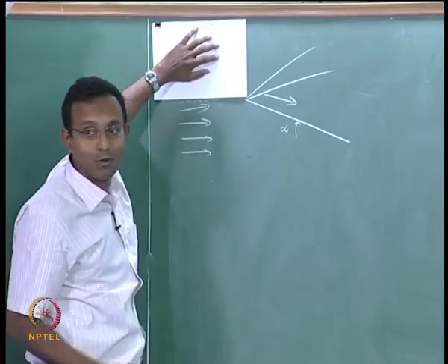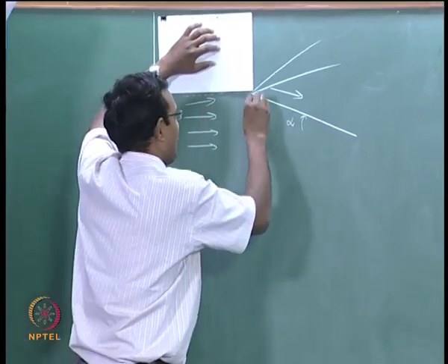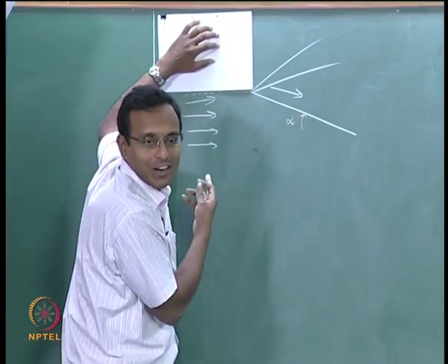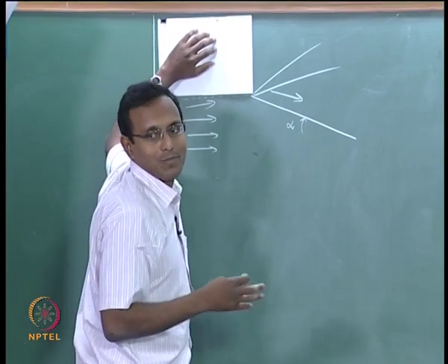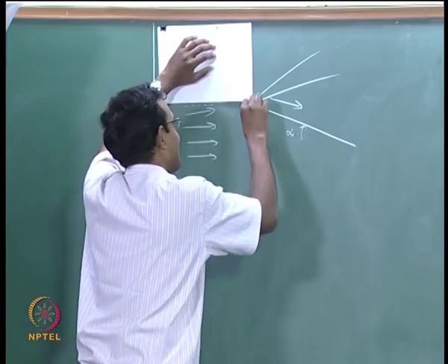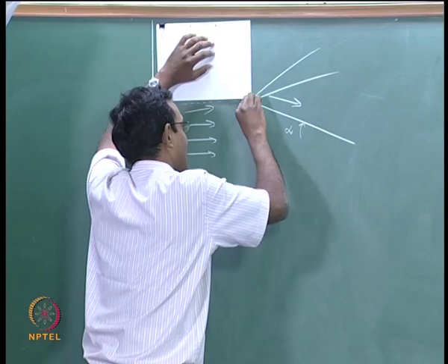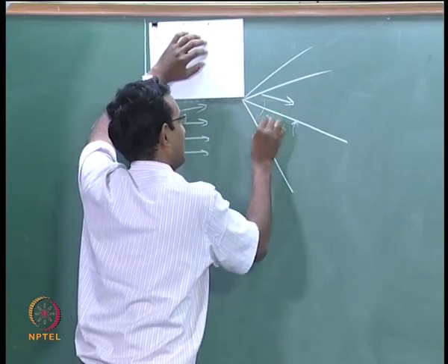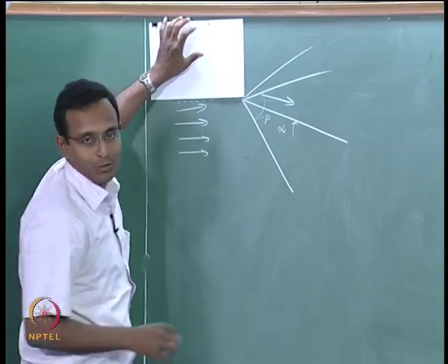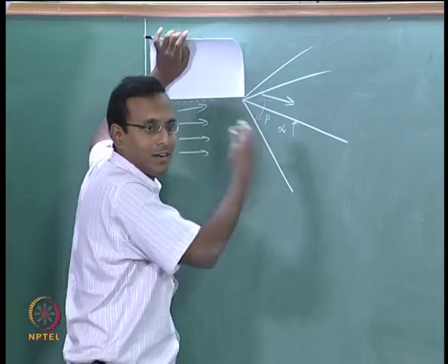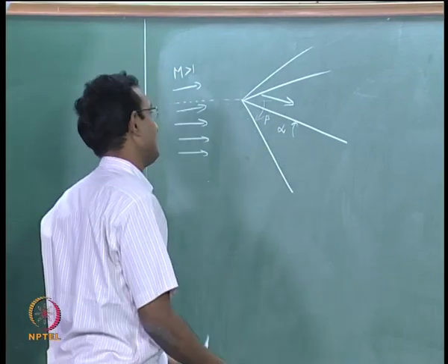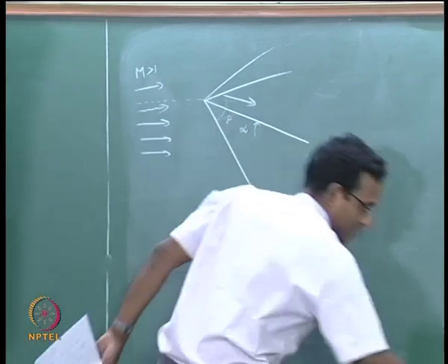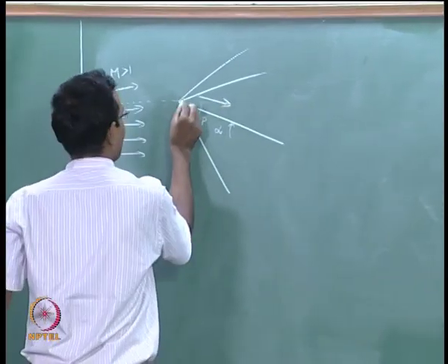So, it is going to have an oblique shock, which is some few classes before stuff. I have to go find the angle. We hope that currently it is not a detached shock. Detached shock case is a complicated case for this problem. We will not deal with it right now. Okay. Let us say it is attached shock and I can find the beta value from there. This is my beta value. I can find it, let us hope. Okay. We can just go find the Mach number and gamma, I can get a beta value for it. So, I have drawn this. Okay. Let us just change the color a little bit for the plate.